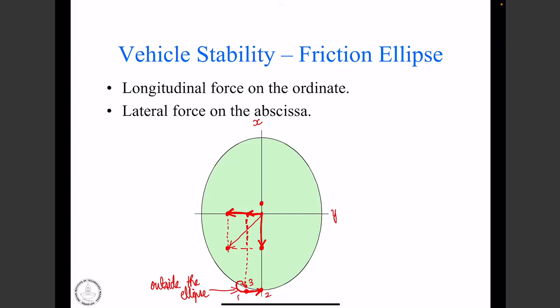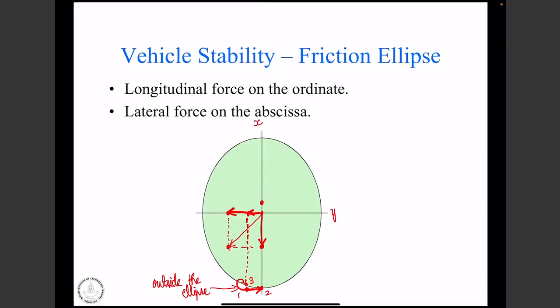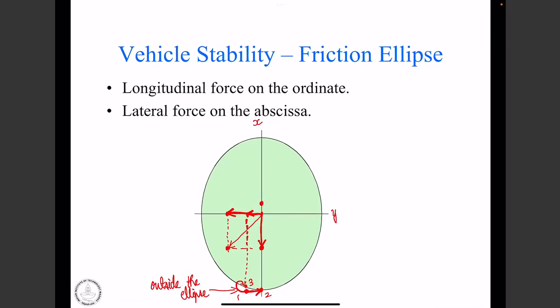So this explains a scenario where we may need the ABS system to perform even on a dry road, under certain emergency scenarios. ABS is typically motivated by looking at wet roads, but even on dry roads it's quite useful. The driver commands some force, but it's not sustainable at the tire road interface.